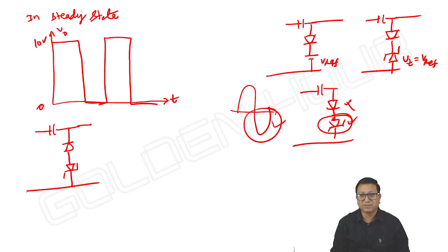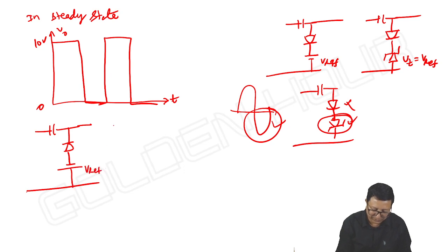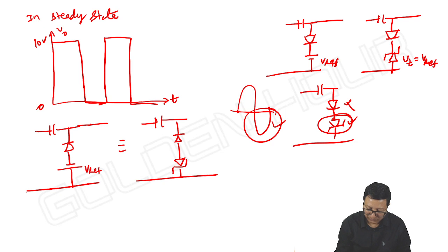Suppose I want a negative reference voltage with a negative clamper, and that too in terms of the zener diode, it is not possible. Again, in a positive clamper, a negative reference is possible. Once the zener diode undergoes breakdown, definitely it will maintain a voltage Vz which is equal to V reference. Students should observe this point also. Vz is equal to V reference.